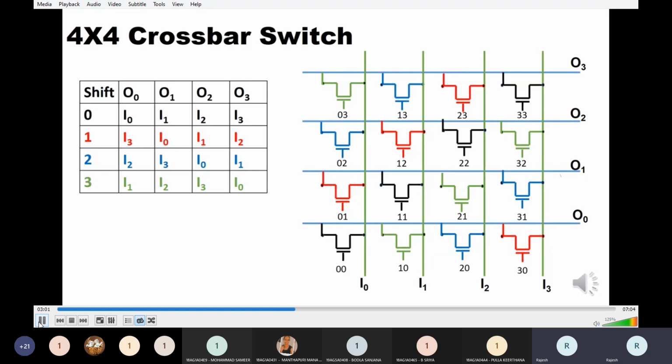Each transistor is represented by a different color for better understanding. The main disadvantage of this circuit is that we have 16 transistors and each transistor has an independent gate connection. It means we have 16 different inputs, which makes the circuit working very complicated. Now let us assume a situation when all the inputs are high.